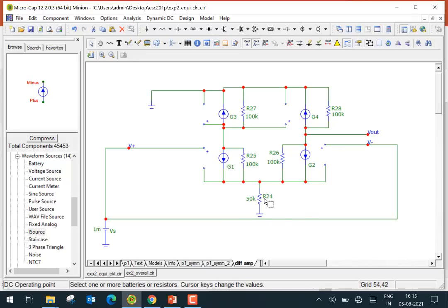So this is actually the equivalent circuit of a 5 transistor differential amplifier. Differential amplifiers, if you would recall, are part of op amps. And this is like the non-inverting terminal, and this is like the inverting terminal here. So we have a circuit like this, and what we have done is we have applied the same voltage to the non-inverting terminal and the same voltage to the inverting terminal, which means that the voltage is common to both the inputs, and we call this the common mode input. And this is where we take the output, V out.